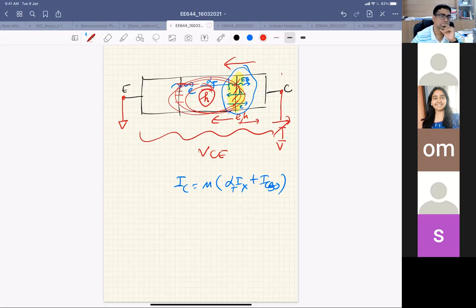So that is what I was saying. By looking at a device, we cannot predict how the breakdown will be compared to some other device. It will basically depend on the physics of that device, ultimately the design of that device, how that device is designed. That's the reason the beta factor is coming into the picture in the equation. If you design a device and your beta is very low, let's say you have a lot of defects in the base, holes are being injected, holes will go into defects and recombine, right? Then there is no way that it will create a positive feedback.